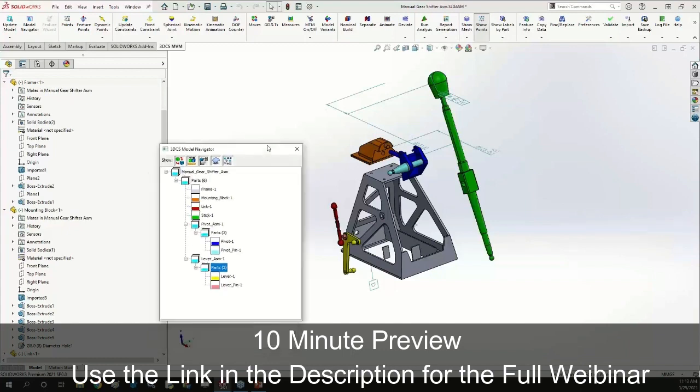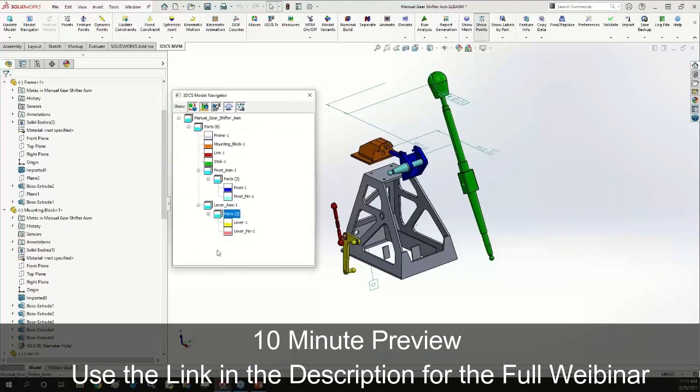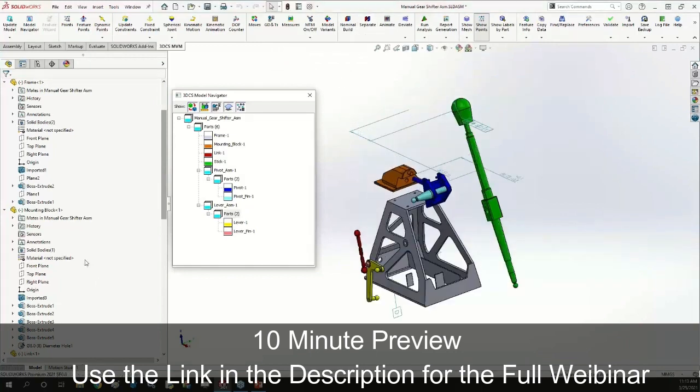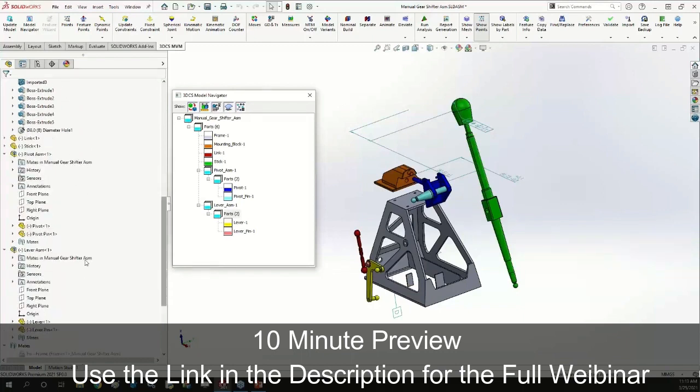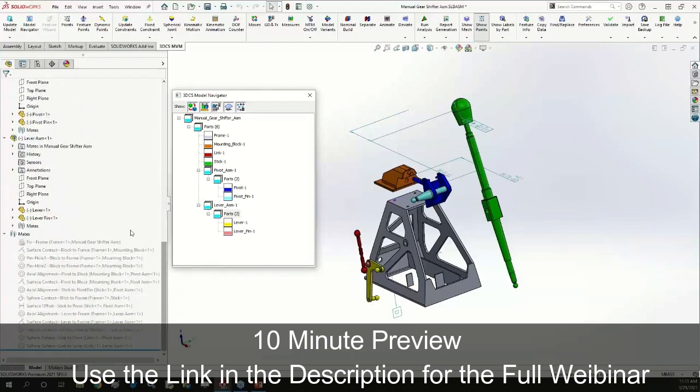So, like I said, at the moment, I have an entirely empty 3DCS model here. So if I select nominal build, 3DCS is going to apply all of my moves. I currently have no moves, so that didn't really do anything for me. I'll separate back out, but really that didn't change anything. So the first thing I'm going to do is I'm going to extract all of my mates that I have in my SolidWorks model. So in SolidWorks, we're using mates. In other programs or other CAD platforms, we're going to call these different things, but the concept's the same. So we have these mates listed down here.